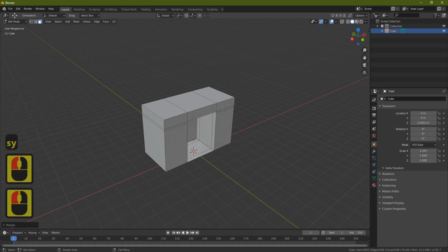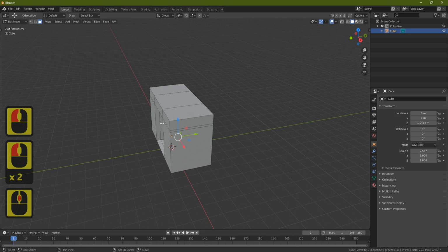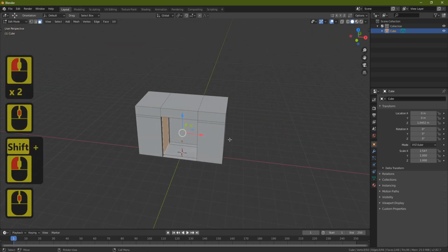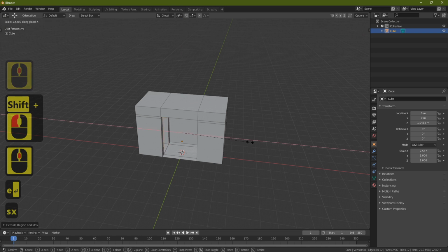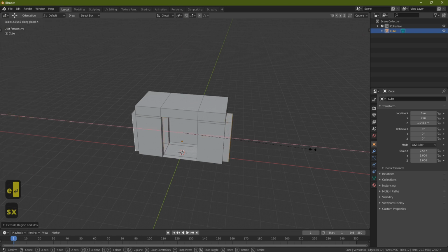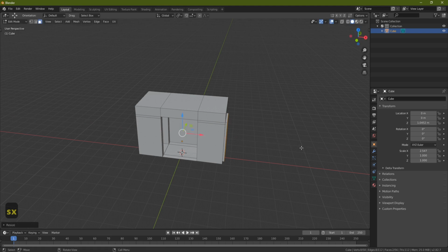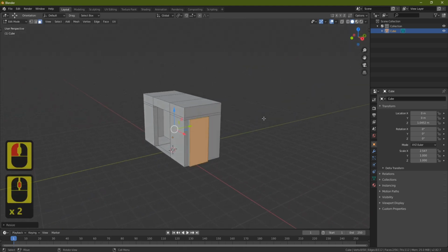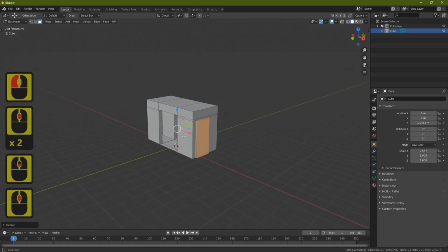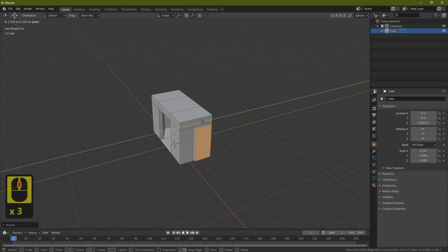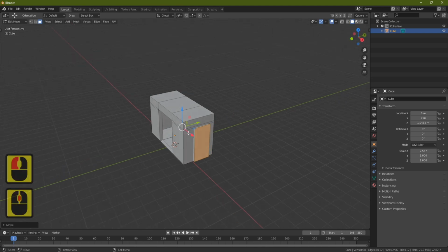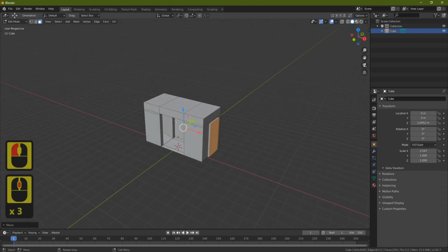Now back to face select, let's grab this face and this face, and now you're going to press E and enter, and then S, X, and just pull them out just till they pop through here like this. And now you can see that if we're looking from here and we've got a saloon door on, it looks like these are actually going into somewhere, and you can actually pull them down like this, so it actually looks like they might be turning a corner or some kind.